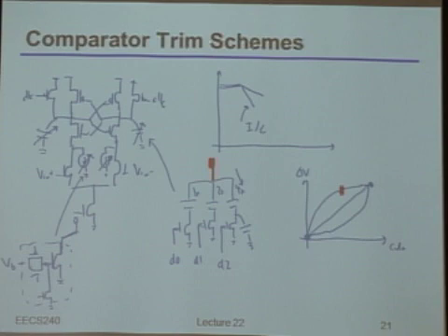So indeed this works, but much like with the previous example, unfortunately, if we needed, for example, 7-bit controllability there, again, we'd have 128 of these unit current sources. And if each one of them had even, let's say, a femtofarad or half a femtofarad or some other pretty small capacitance, once again, we're directly loading the outputs of our comparator with that capacitance. Bad news. It causes us to spend a bunch of extra power.